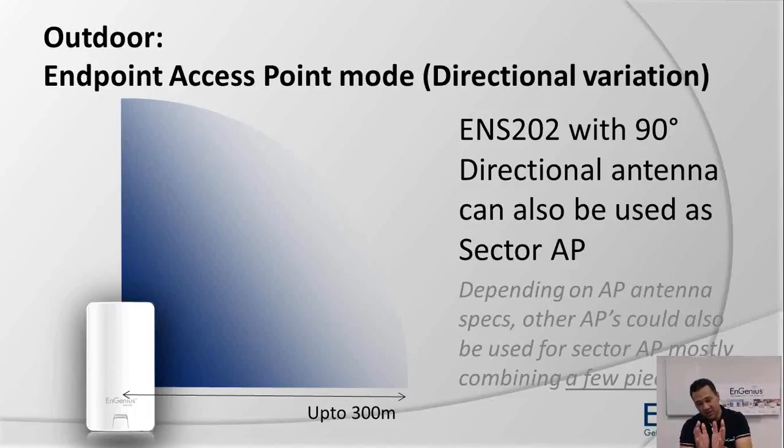Normally a directional antenna will have further distance but on a smaller angle, and in this way you can have more sectorized and further coverage using separate access points for just a part of the sector of your deployment.